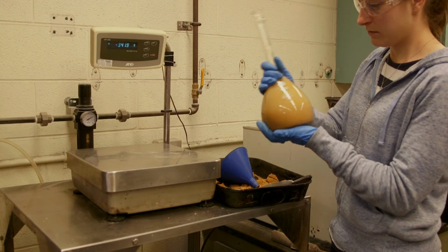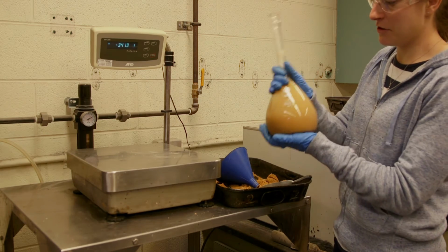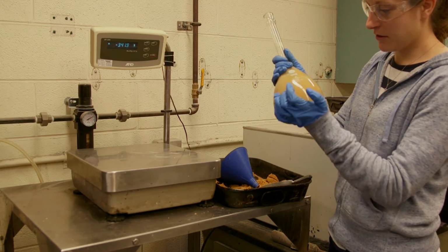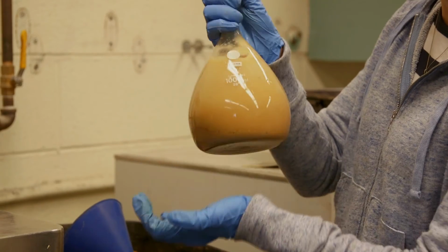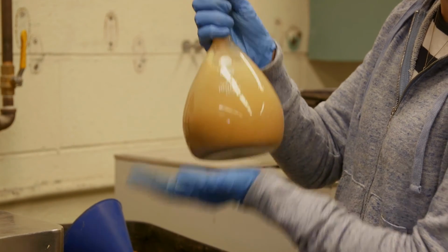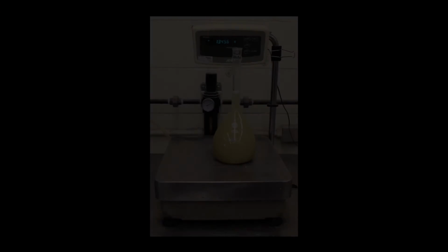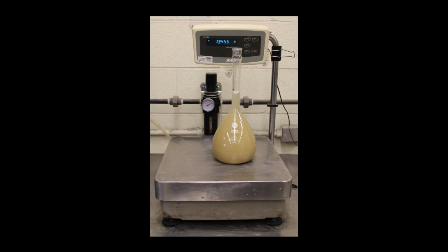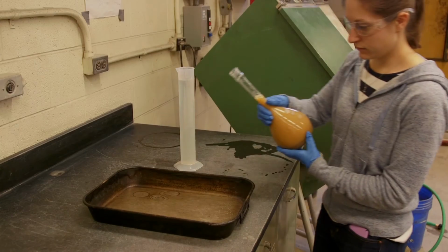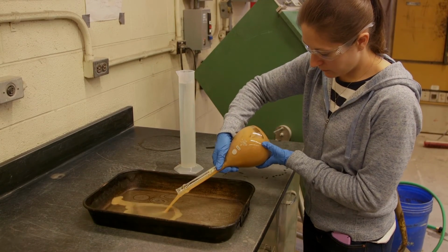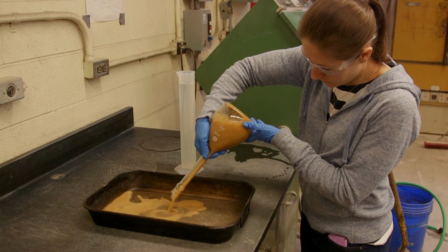Agitate the pycnometer for 15 to 20 minutes to eliminate air bubbles and then determine the mass of the pycnometer. Add additional water to return the pycnometer to its calibrated capacity. Place the flask with aggregate and water onto a scale and record its mass. Remove the aggregate from the pycnometer using excess water to flush all aggregate from the pycnometer.